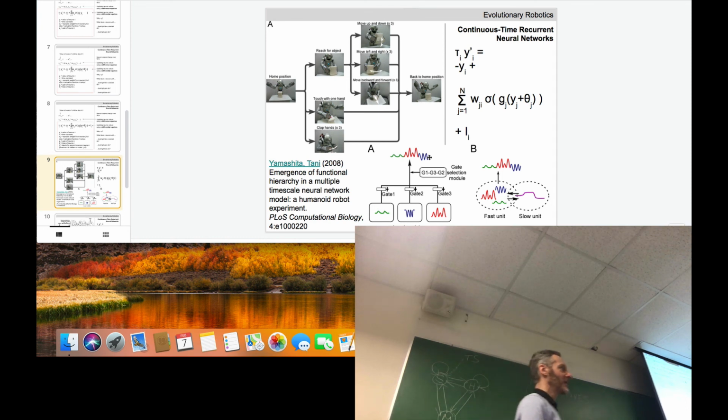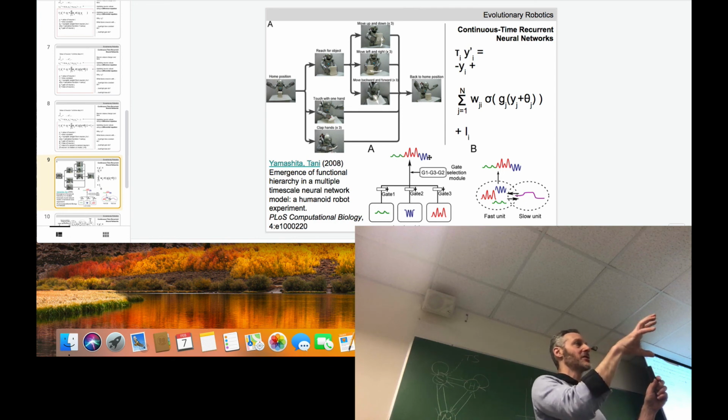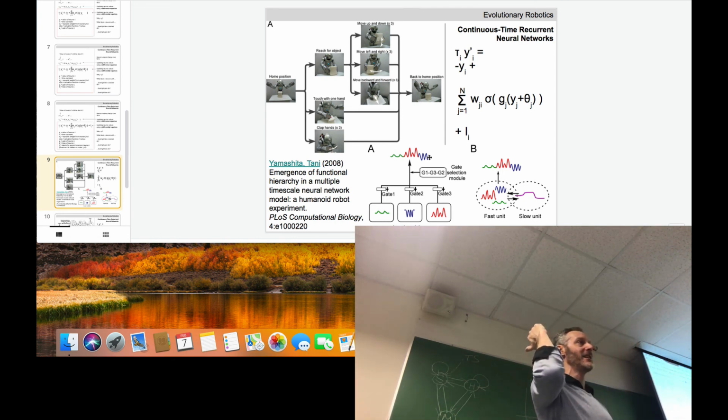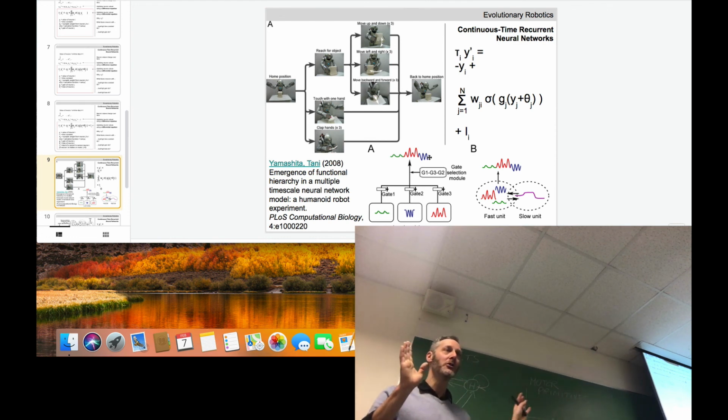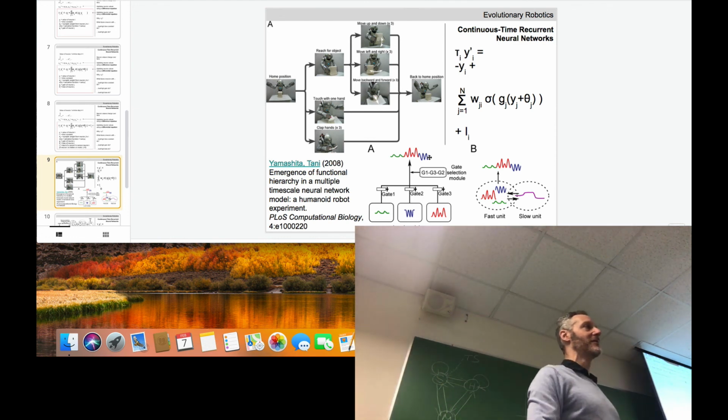If you remember all the way back to the beginning of the course, when we talked about the history of AI, in the 1980s, Rod Brooks introduced the subsumption architecture, the neural network that's running inside your Roomba at home. Clean the floors, move straight, unless I sense that I'm about to go over the edge of the top of the stairs. Suddenly, a different network seizes control of the Roomba, causing it to turn and head in the other direction. Once it does, that subnetwork lets go of the Roomba, and the normal floor cleaning subnetwork takes over again. That's the same thing that we see here. In the Roomba, it's corporate secret, so who knows, but there's probably 2 or maybe 3 of these subnetworks.